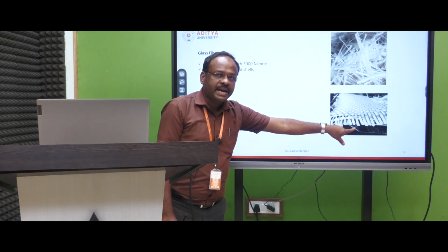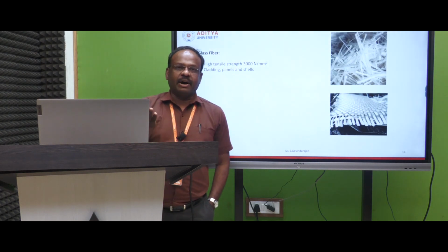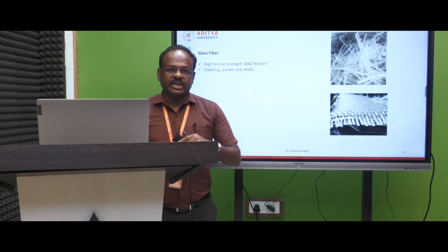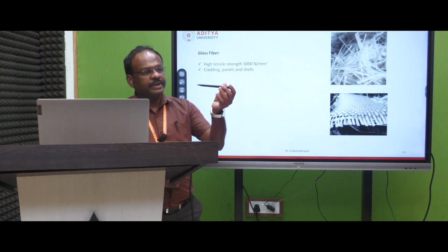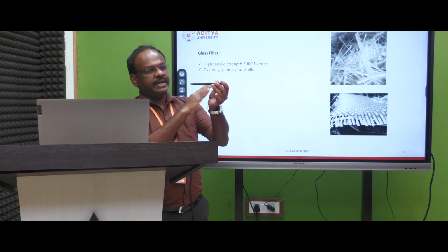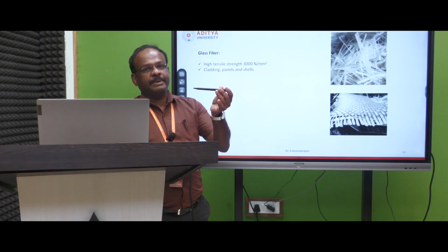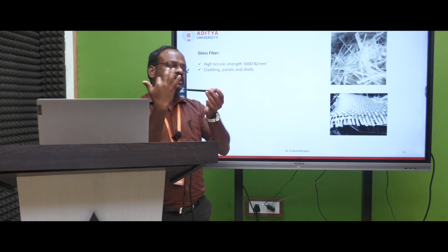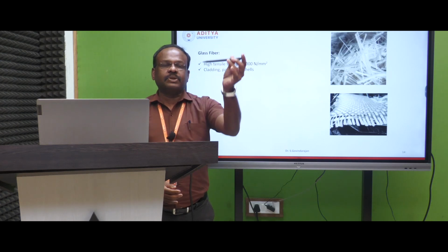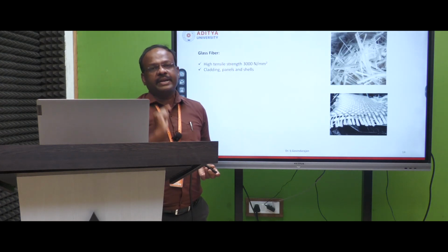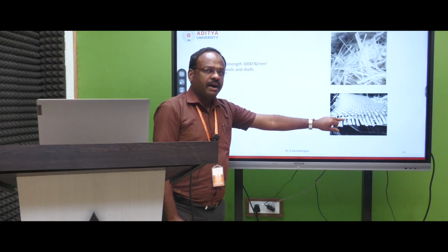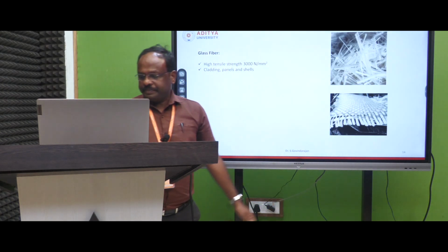Where is this mat fiber used? Mainly on the outside of the structure. Suppose the structure has a beam, what do we have to do, how do we make it with the fiber? For the beam, only the bottom side and the two sides, front and back, are wrapped with this material. Why don't we go for the top side? Because the beam is attached to the slab, so it is not possible. Only U-shape wrapping is possible, right? That type of fiber is called electrical grade glass fiber or S glass grade fiber.